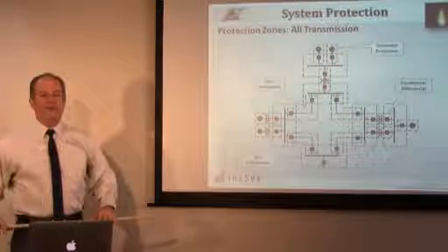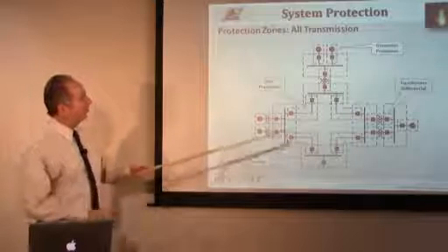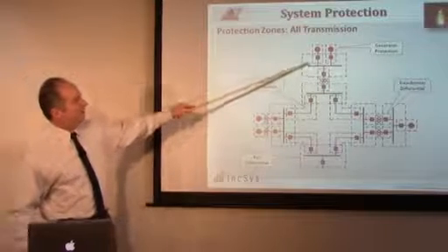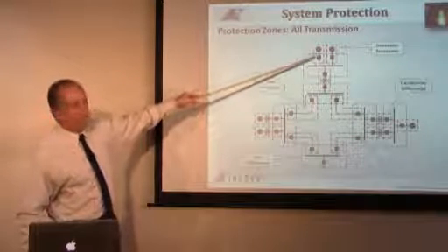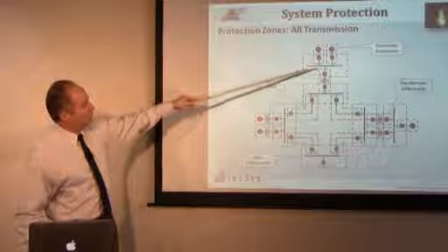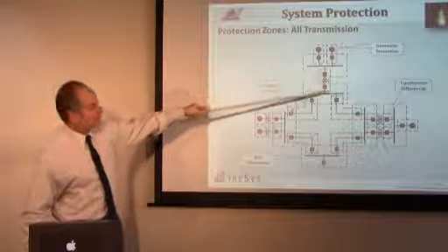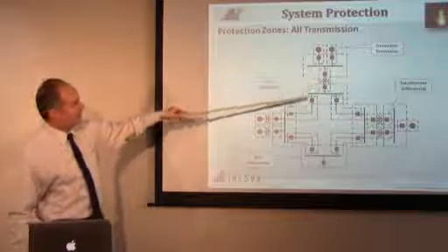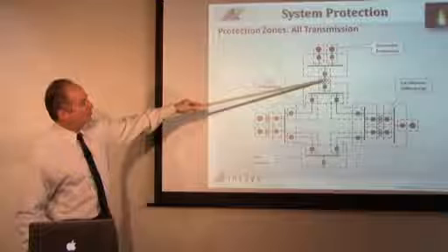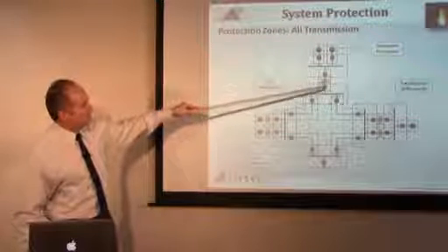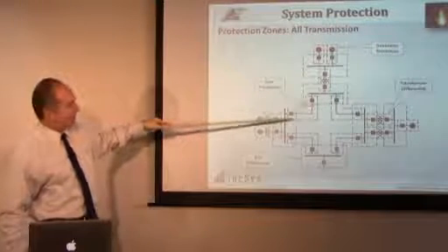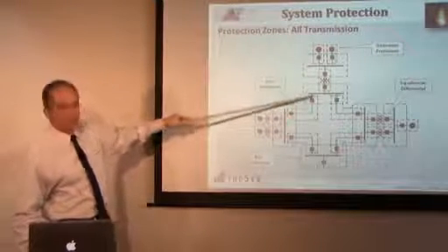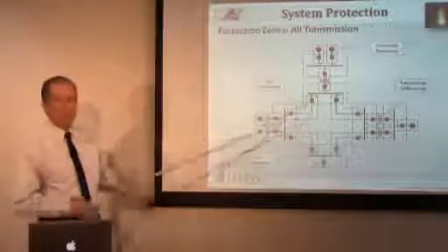When you put it all together and look at an overview here, bus differential is overlapping generator protection, which is overlapping transformer differential protection, and this bus is overlapping the differential protection of the transformer, and it's overlapping the line protection. So we use CTs on the opposite side to give overlapping protection, and that's basically how transmission is set up in a substation.